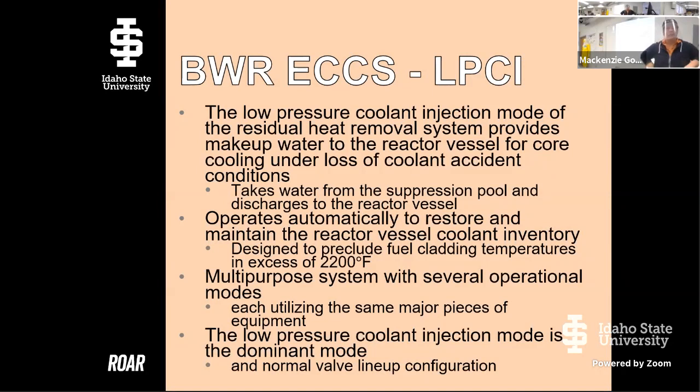What temperature is the clad usually at? Usually it's half that. Usually your limit where you start having to engage in some emergency procedures is at half that melting temperature. So you want such a margin of safety, and then your operational temperature will be down around 500 to 700, right? So when you get to about that 1000 or 1300, you're going to have to start activating operational modes to keep you from going up further in power and temperature, right? The reactor will do some automatically.